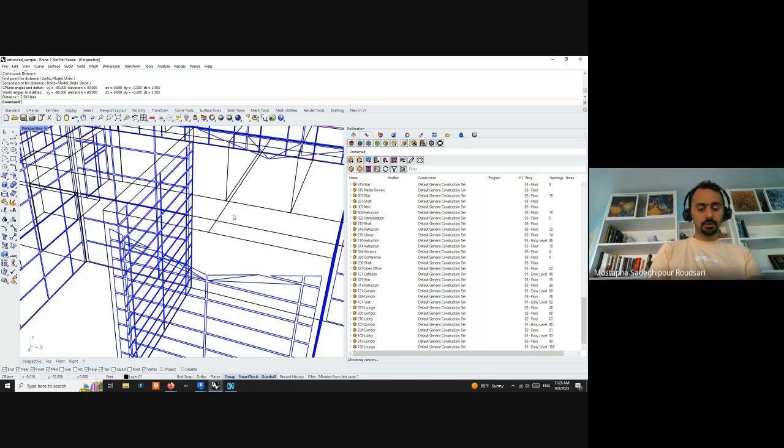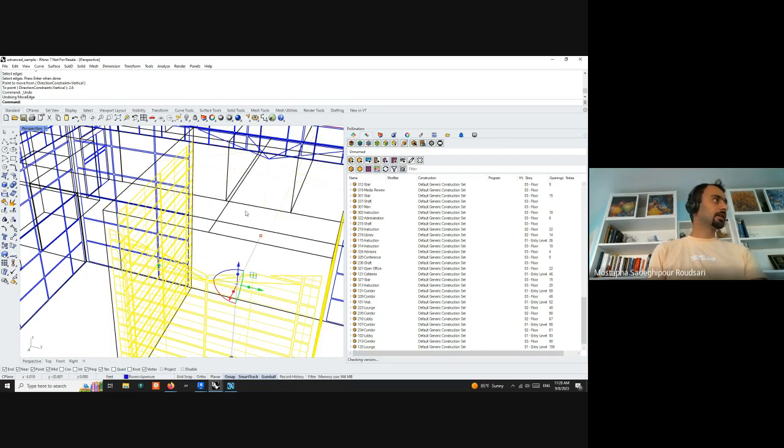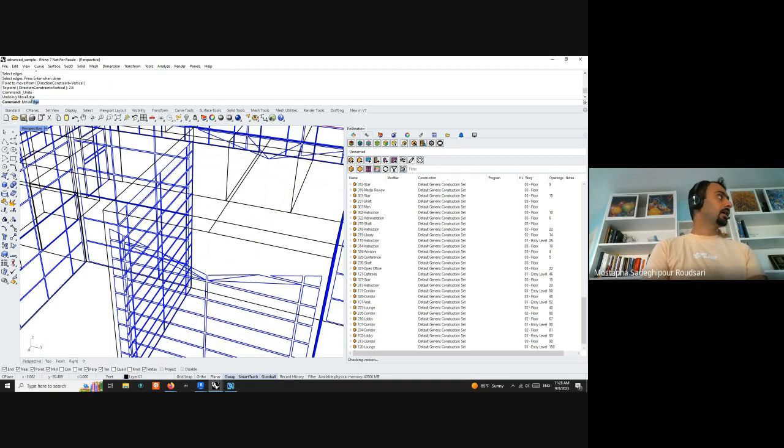So I'm going to move edge, and then select this edge. And we have video tutorials on how to edit all this stuff in Rhino. So I'm going to do 2.6. Is it what I said? Oh, I should have done minus 2.6. So move edge here, here.